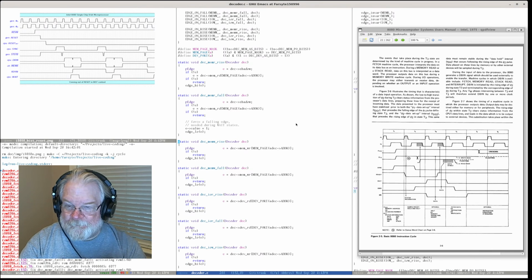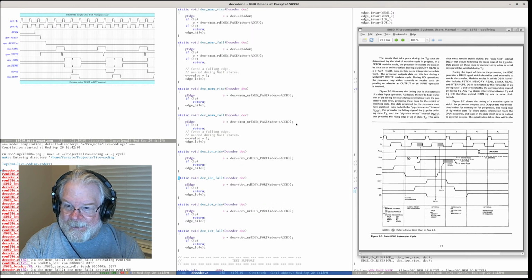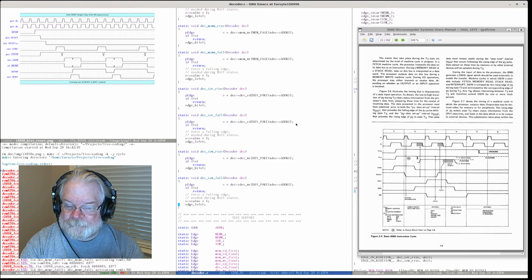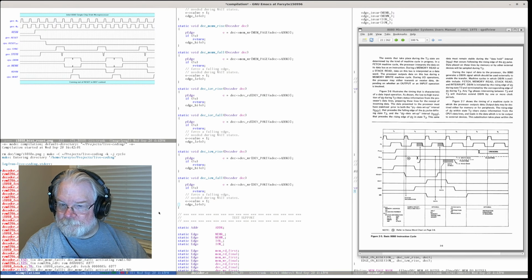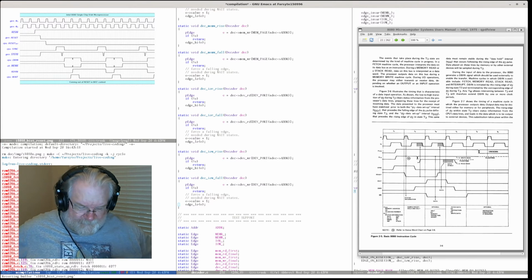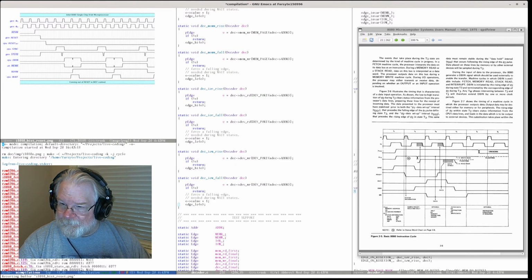We may have wait states on other things as well. So these other places where we do edge low, I'm going to force it high first. I am not sure if we have wait states during write. I'm going to have to check that. I think we do. Anyway, I will force the edge here in decoder just in case.